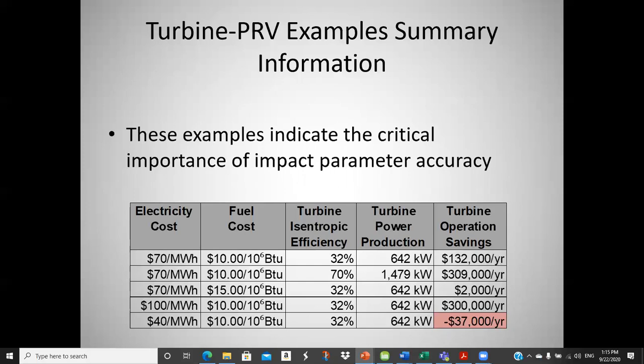I would say a rough and dirty number for the cost of this depends a lot on your electrical infrastructure and what you have to do to integrate this generator into your switchgear to be able to absorb all this electricity inside the plant. But somewhere between $1,200 a kW and probably $2,000 a kW on the project cost is reasonable. I think I told you guys to use $1,500 a kW.